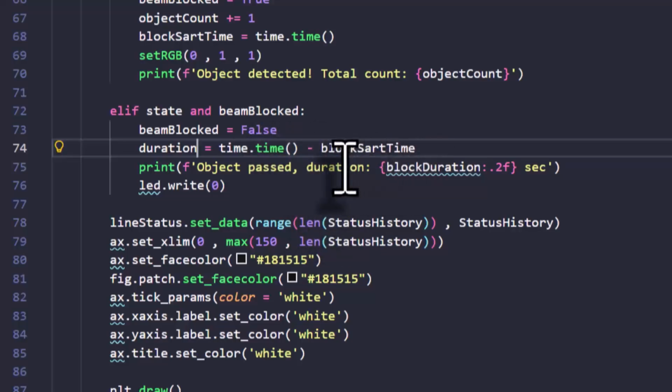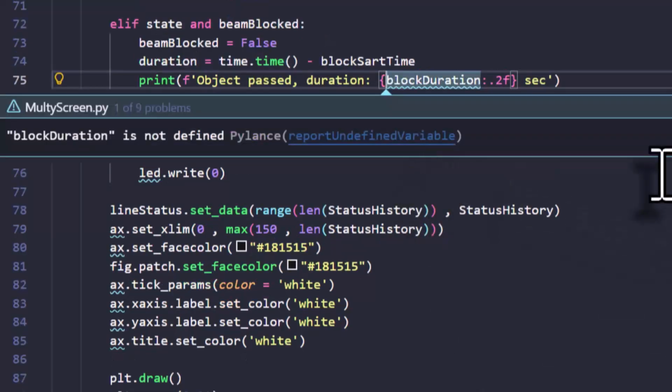Now I have to add another if statement. I want to say, for example, if the sensor doesn't get blocked, or doesn't sense any object for more than 2 seconds, it means, for example, that our conveyor is stopped, or that we missed an object, our product, our goods, because no object blocked our sensor. So we want to send an alarm. So now I have to use an if condition here.